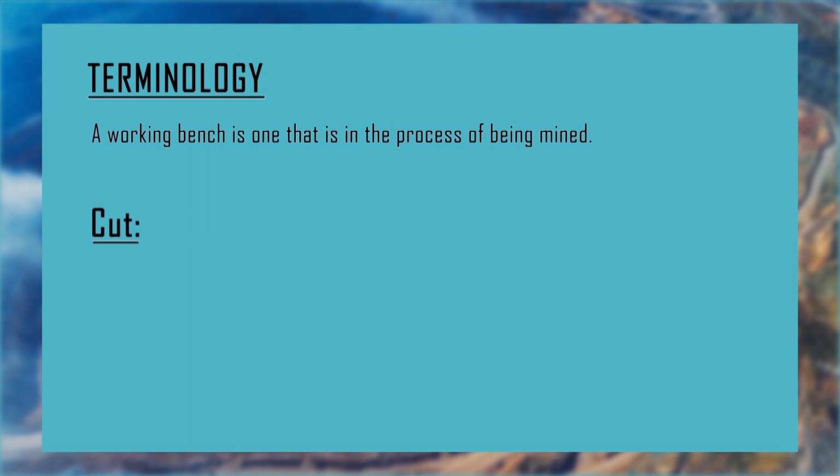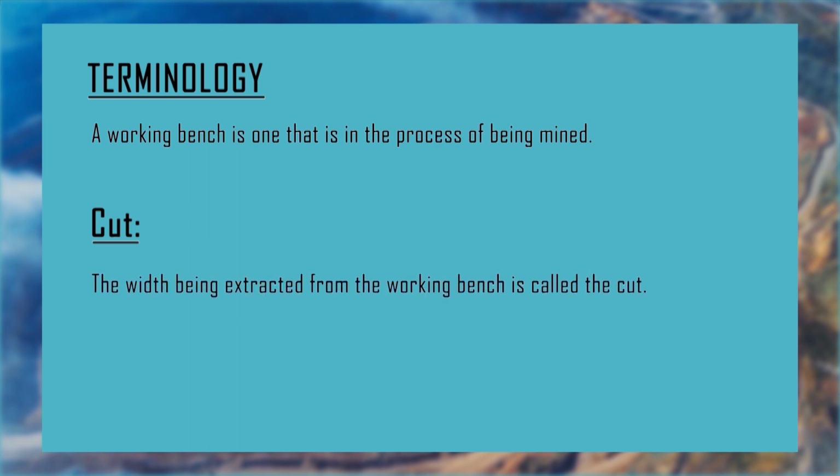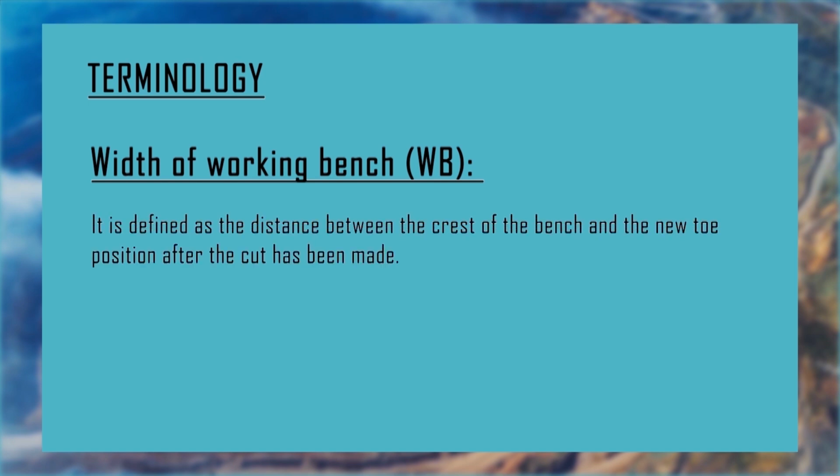The width being extracted from the working bench is called cut, meaning that width of bench that is extracted. Width of working bench is defined as the distance between the crest of the bench and the new toe position after the cut has been made.